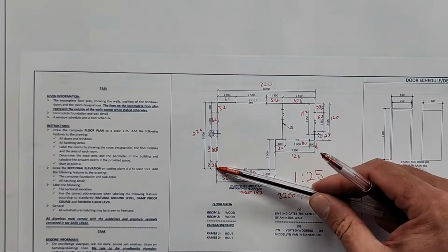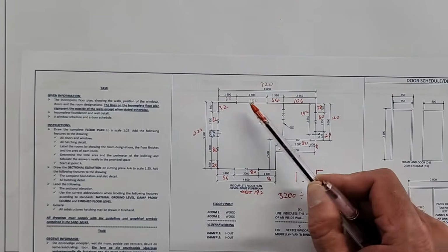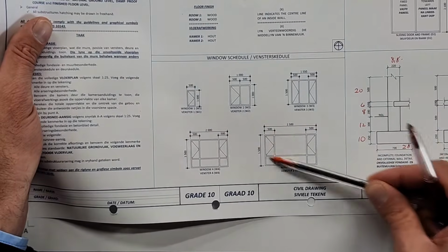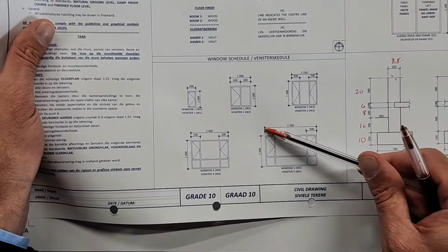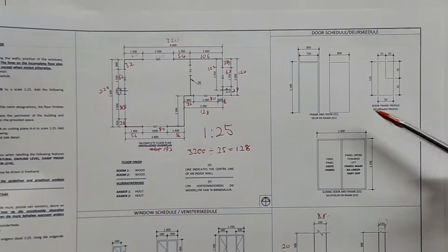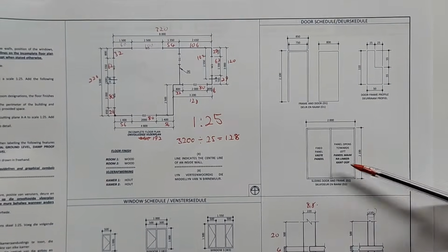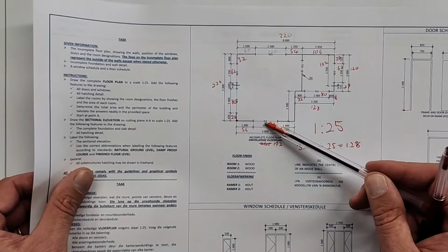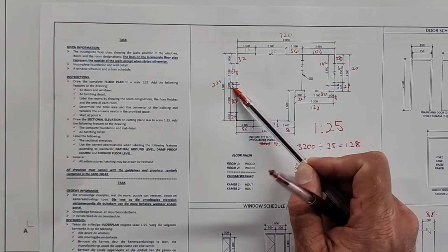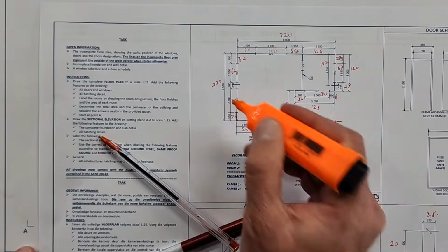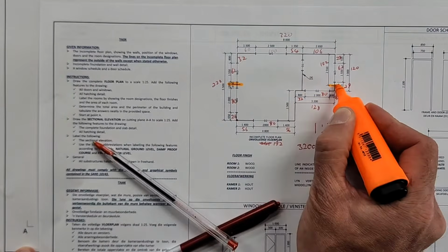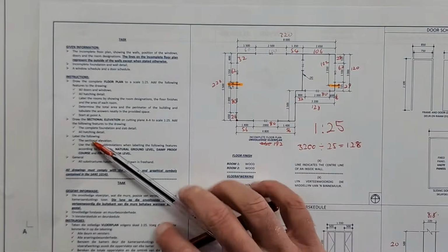I'm going to start off with this outline in construction. The W5 indicates window 5, and when I draw that, I'm going to refer to the window schedule for its measurements, specifically its width. Then door 1 refers again to D1 here. We also have a sliding door labeled D2, and that is its position. So they've indicated the positions of the various doors. They've also indicated the cutting plane. If you look there, there it is. It's a cutting plane that goes through the external wall, through the internal, through the external, and we'll do that sectional elevation as well.